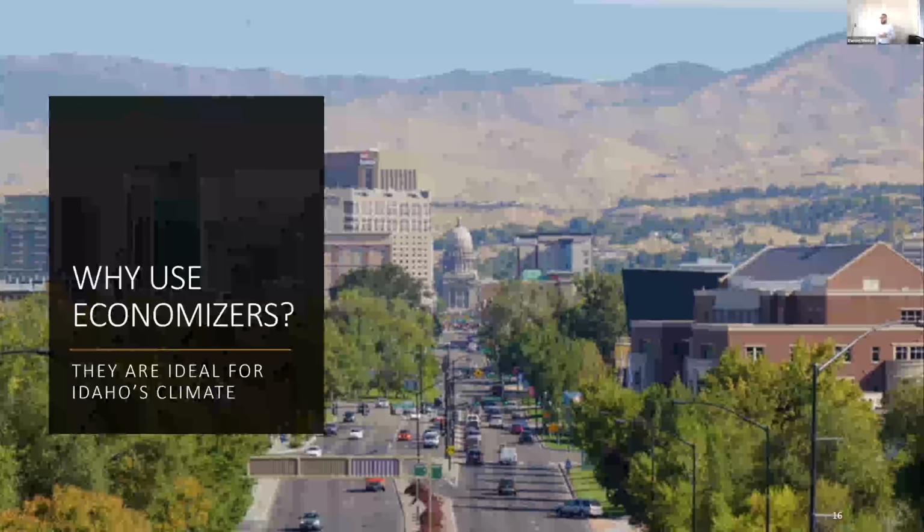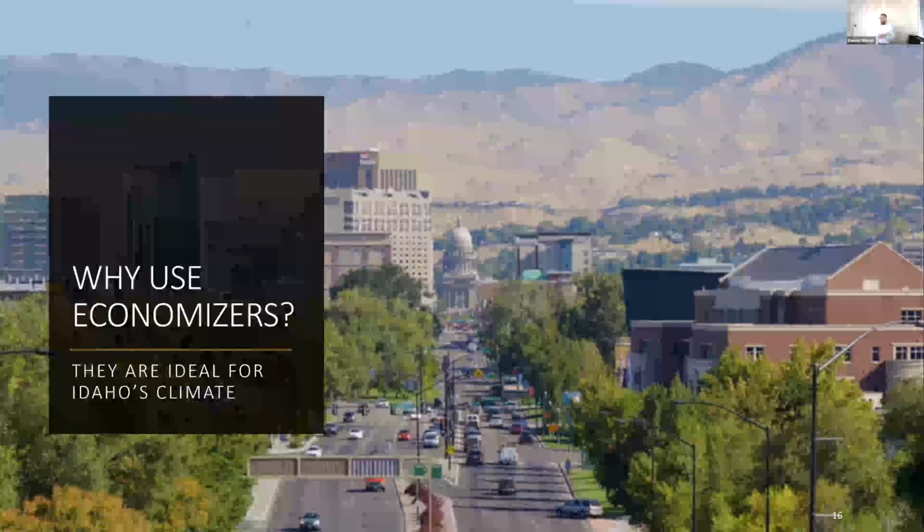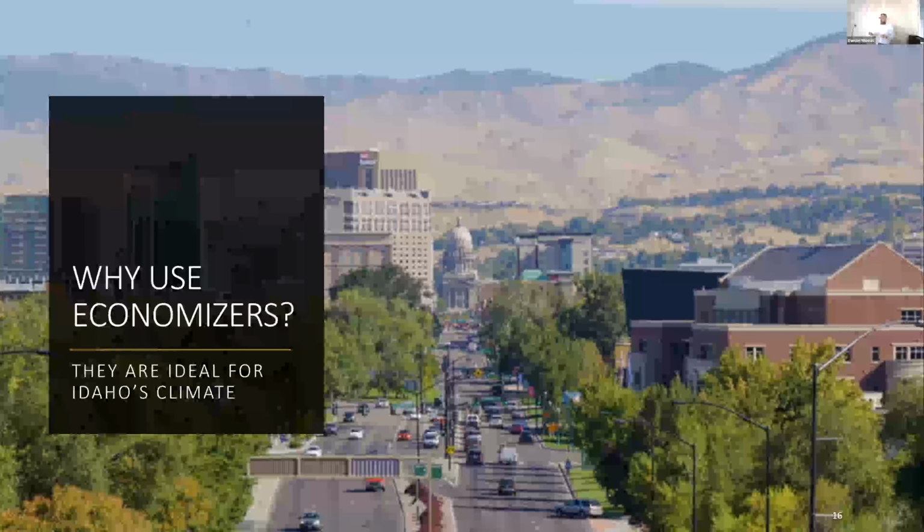And the facility managers were kind enough to give us direct access. And so we started messing with it, and we were looking at it on a morning like today. I guess it was a summer day. It was supposed to be in cooling mode, and we should be bringing in some outdoor air because our sensor was saying it's like 60 degrees outside. And instead we're just trying to cool down the 70-degree indoor air and recycling. We should just bring in some more fresh air and cool it down. And as soon as we did, we saw all the thermostats in the building pop up to like 80 degrees. People were probably miserable. So very quickly, within 5 minutes, we're like, nope, not going to do that.